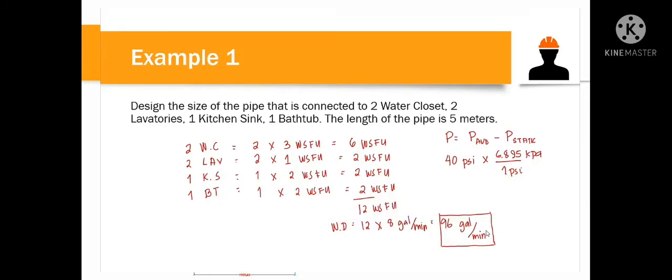Okay? So, now for service pipe, we have 19 millimeters, or this is 3/4 inch. And for branches, we also have 19 millimeters, which is equal to 3/4 inches. Now, again, in service pipe, the diameter should not be lesser than 19 mm, which is okay.